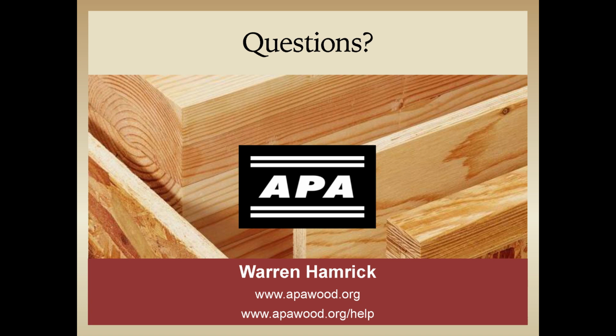Yes. Wonderful. Another question that came in is, when you talked about the axial strength of the 2x4 versus 2x6 stud, do you know what stud height was used in those calculations? Yes. So just a brief refresher, we talked about the axial compression between the 2x4 at 16 versus the 2x6 at 24. And the 2x6 at 24 was actually 2.05 times stronger than the 2x4 at 16, and that was tested at a 9-foot stud height.